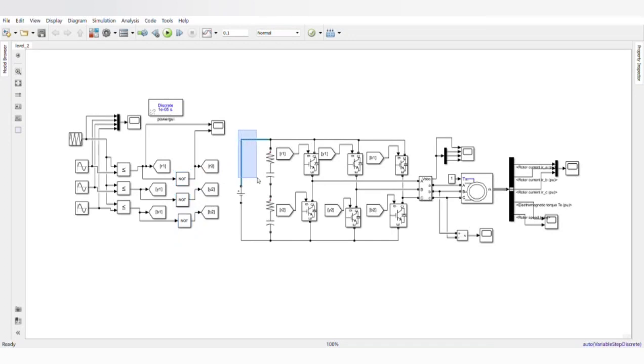And this is the main circuit of a two-level inverter. That main circuit consists of a DC voltage source to produce the three-phase output voltage with two levels, and a series RLC branch is used as an RC filter, which is used for filtering of harmonics in the generated current, and IGBTs are used as switching devices to perform the required operation. This is the application of a two-level inverter. These blocks represent the asynchronous machine, which is the type of squirrel cage induction motor.